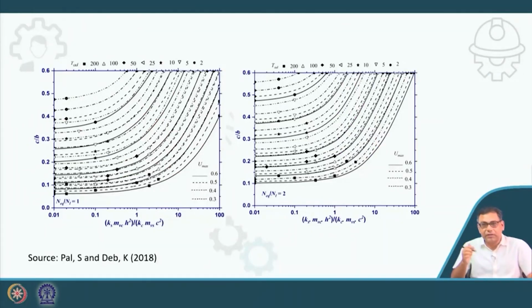Now, we have discussed four effects: the stiffness of the column, the permeability of the column, the smear effect and the clogging. Out of these four effects, clogging will not be incorporated in the model.